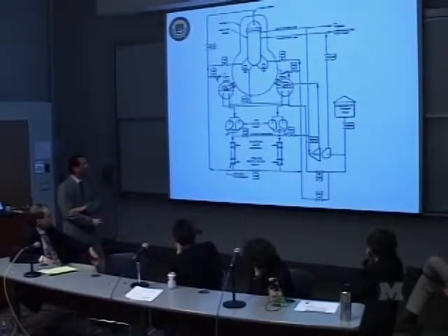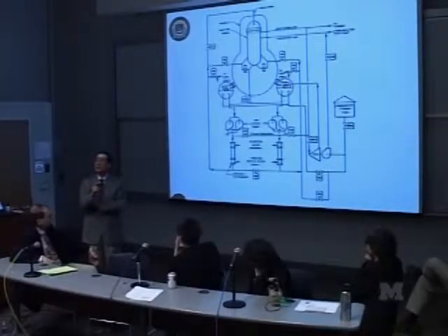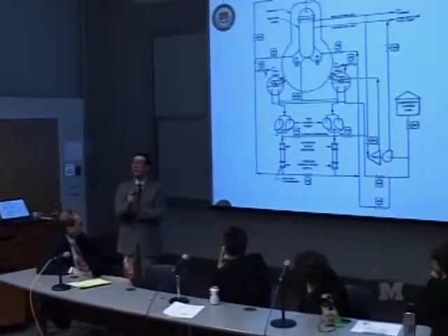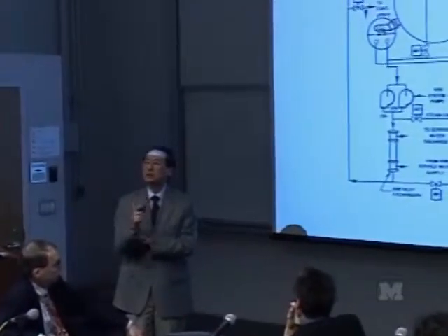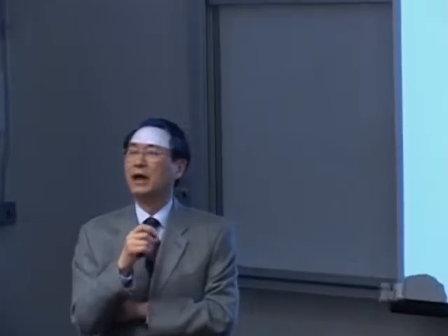So up until that time, although when diesel generators stopped functioning, we lost station power, and that's known as station blackout event. And so the way I describe the whole sequence event is due to the earthquake, the plant suffers station blackout event. And the backup steam-driven pump worked for about half day. And then due to tsunami and the other events of nature, we lost the cooling capability.